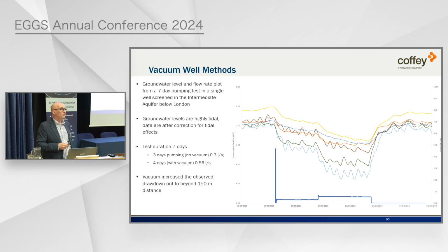It's true, I have done vacuum on other projects where the vacuum has been tremendously ineffective, probably because I think the wells were clogged up. But here they had a good well design and the vacuum was quite effective.